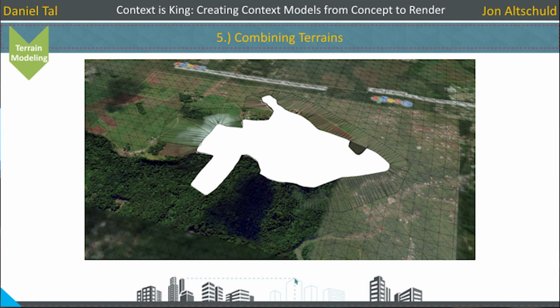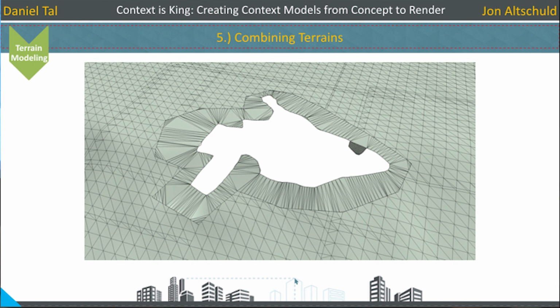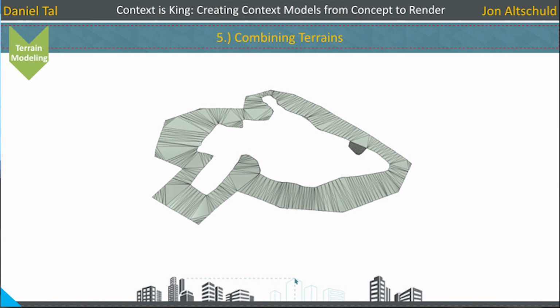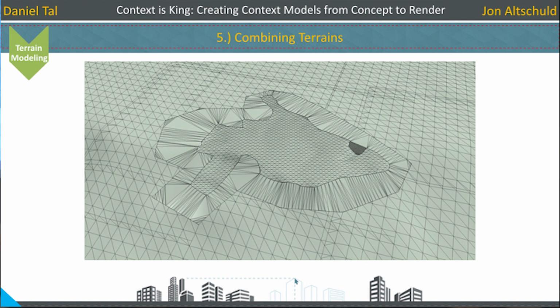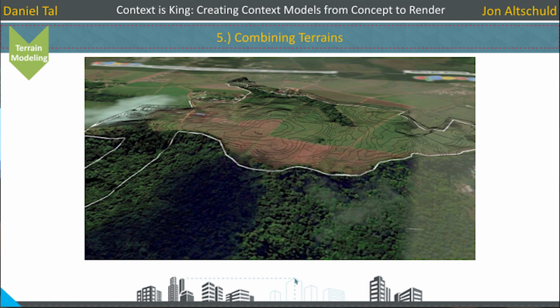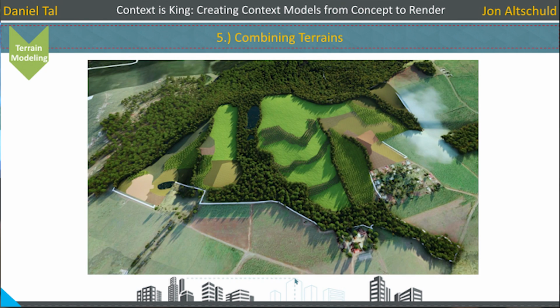Here's the location tool terrain. So here's our proposed grades. Here's the location tool terrain. And here's the skirt around it. And so the edges that we used here were then used and connected to this. And the result is this skirt all the way around the site. You can see what it looks like here. And mesh from contours. There's the skirt itself, this transition zone between the two models. There's the mesh from the proposed grades, and there's the result. And again, high resolution aerials combined with it, and put a boundary in there, and we get to produce this.